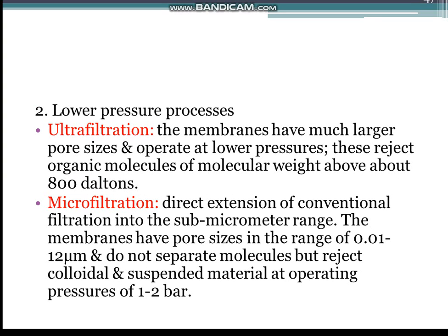Second, lower pressure processes. Ultrafiltration is similar in principle to reverse osmosis, but the membranes have much larger pore sizes and operate at lower pressures. Ultrafiltration membranes reject organic molecules of molecular weight above 800 daltons and usually operate at a pressure less than 5 bar. Microfiltration is a direct extension of conventional filtration into the sub-micrometer range.